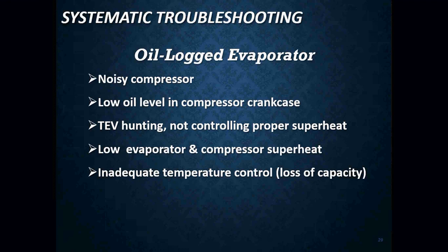When it comes to oil-logged evaporators, the compressor, the first telltale sign is the compressor is going to be noisy. It's going to have a weird sound to it. Low oil level in the compressor crankcase, especially if you are dealing with a semi-hermetic compressor that actually has an oil sight glass on it where you can see the oil level inside the compressor itself.